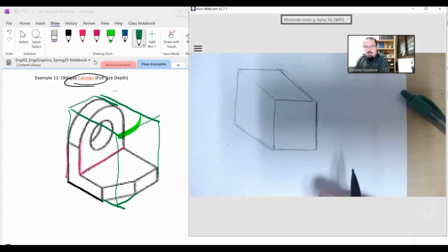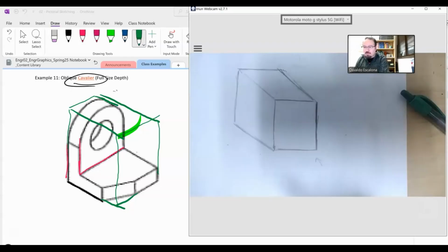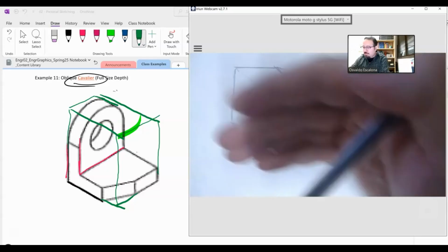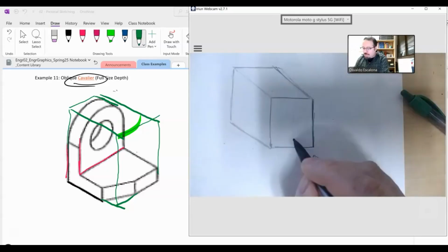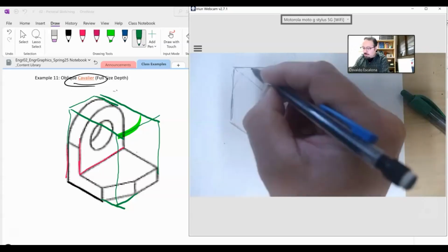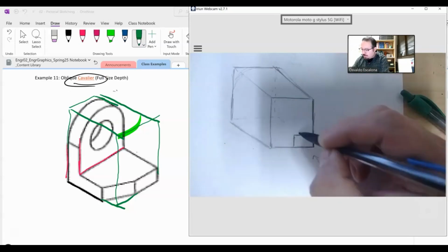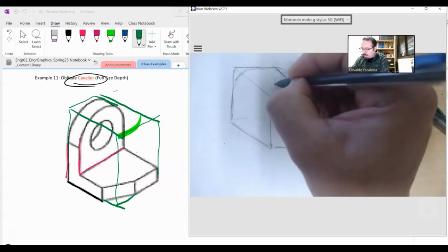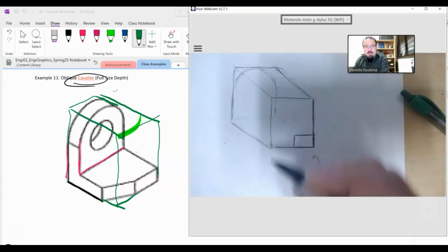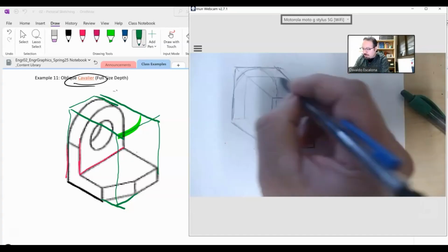Next thing, I know that whatever I see on the front view or anything that's parallel to it, and again, in this case, I want to project anything parallel to this view, will be a true size. So if I go there, this one is the front of it, and then the back one will be, let's see if I can give it a depth here. Anything that is parallel to it will be a true size. For example, I can go and give it a shake there, right? And then I can offset by the distance. Let's say there is an offset about there.